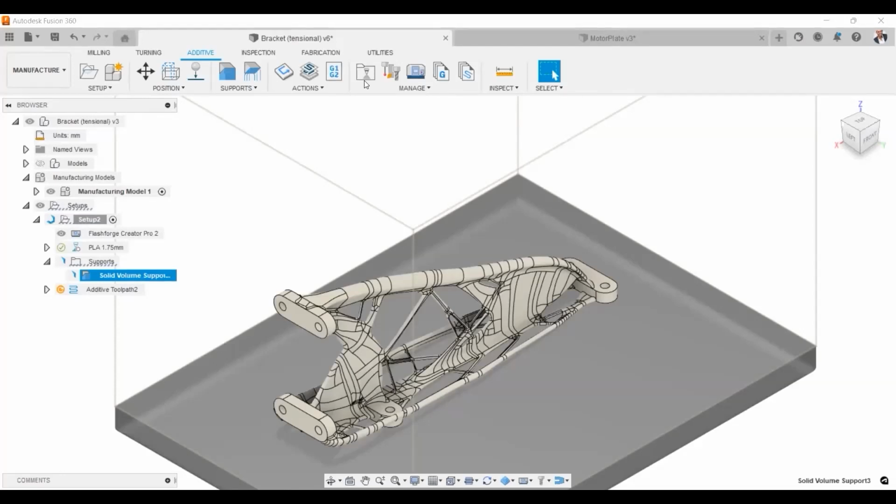So maybe you're bringing in ABS plastic of 2 mm, 3 mm, or 1 mm, or sheet metal of 1 mm, 0.8, 0.5, 0.6 mm, and it depends on the type of laser cutting you're doing, whether plastic or metal, the most common being metal. Metal goes through sheet metal fabrication, so it follows the rules of sheet metal fabrication. Laser cutting works with sheet metals, and you can cut and fold them, like generator enclosures and the old desktop computer PCs. They're all sheet metal, cut, drilled, folded and tied up, so that uses laser cutters.